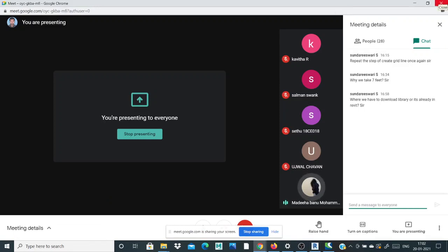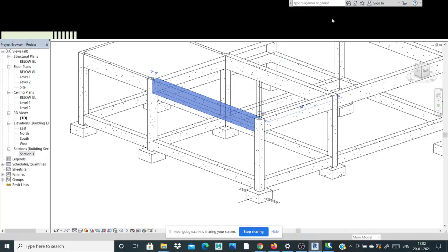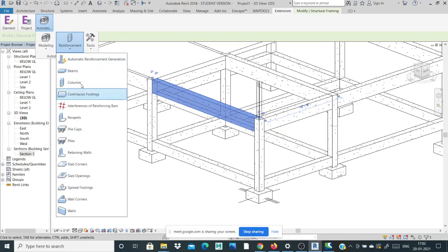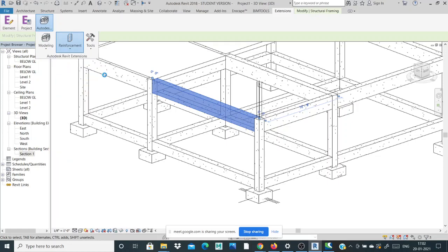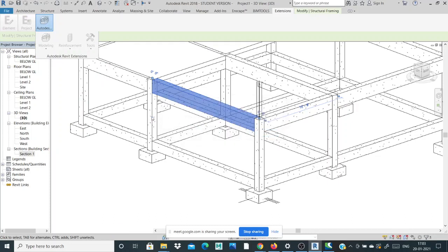How to calculate the development length of the rebar? Yes, ma'am, there is an option for this automatically. In the detailing process or the calculation process? Both. The calculation process is as per the SP 34 code book; refer to it for all the detailing. Otherwise, if you go to reinforcement detailing, beams, columns, and click this, all the values are there. Once you calculate manually, you can put the same value here.